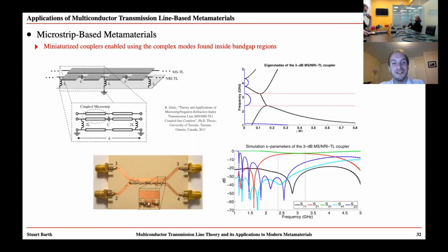Oh, thank you for the great question. Yes, we can in fact do that. While we typically use linear components, just capacitors or inductors, etc., the ABCD formalism that we use to analyze these structures actually allows us to put any arbitrary component in, as long as it's describable in terms of its voltages and currents by this ABCD formalism. So yes, we can indeed put a nonlinear component in. We would have to include the effects of doing a sweep on, let's say, the level of voltages and currents, etc.